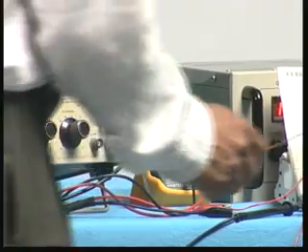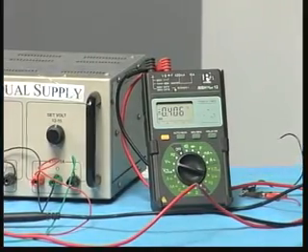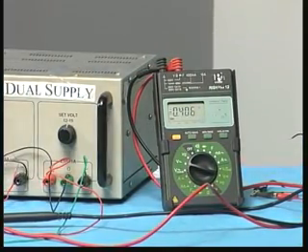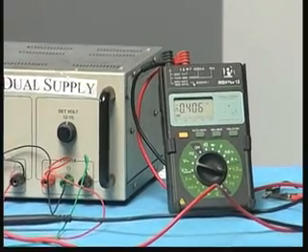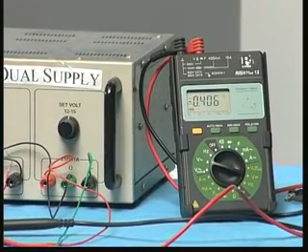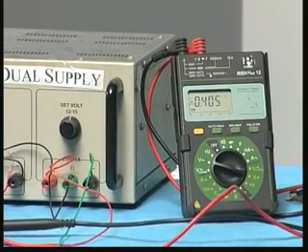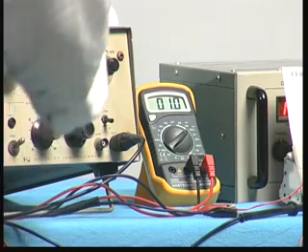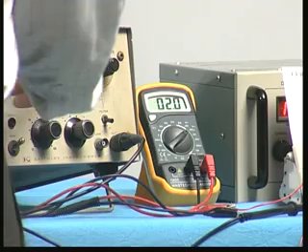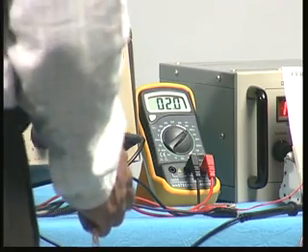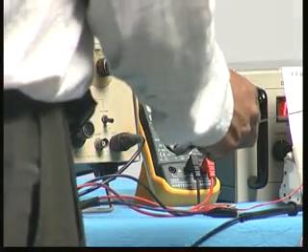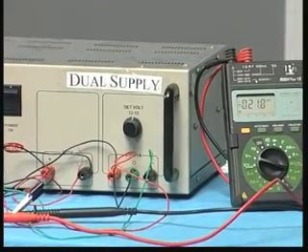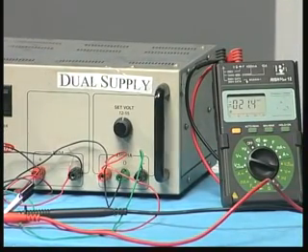You multiply by 10k, you get about 406 millivolts or so. So you can see this current is converted into voltage. Now if I change the range, for example I will bring this to 0 and have 1 or 2 microamperes. For example I have kept 2 microamperes here. 2 microamperes multiplied by 10k should give me 20 millivolts. So what you get on the millivolts range is about 21.4.